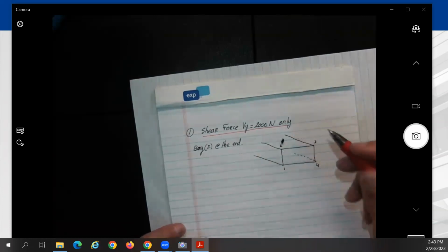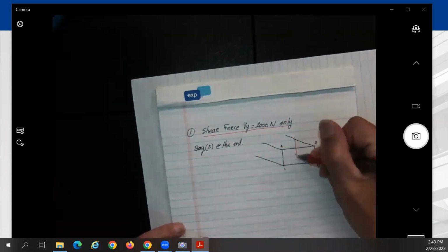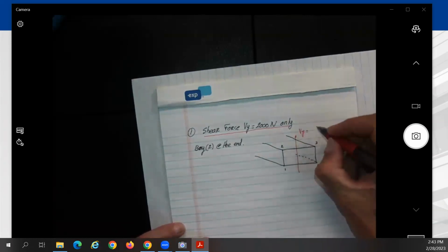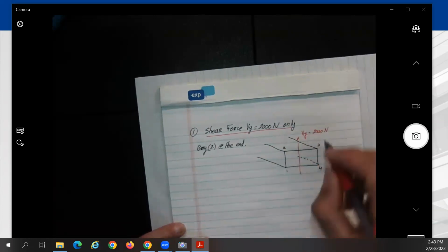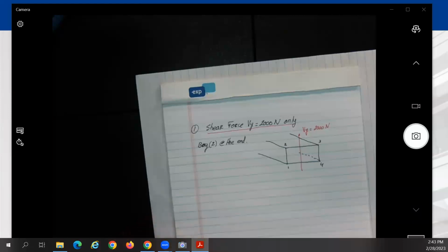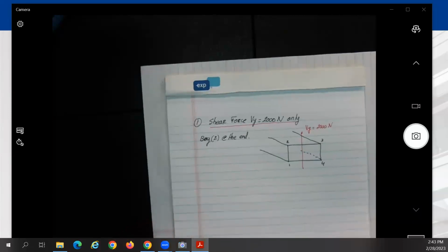We say this is going to the shear center, so I'll just make it in general here, going up. Okay, so now you remember, what did we say at the beginning of the semester is that if you have a force, only the members that will be on the same direction of the force will be resisting the load.